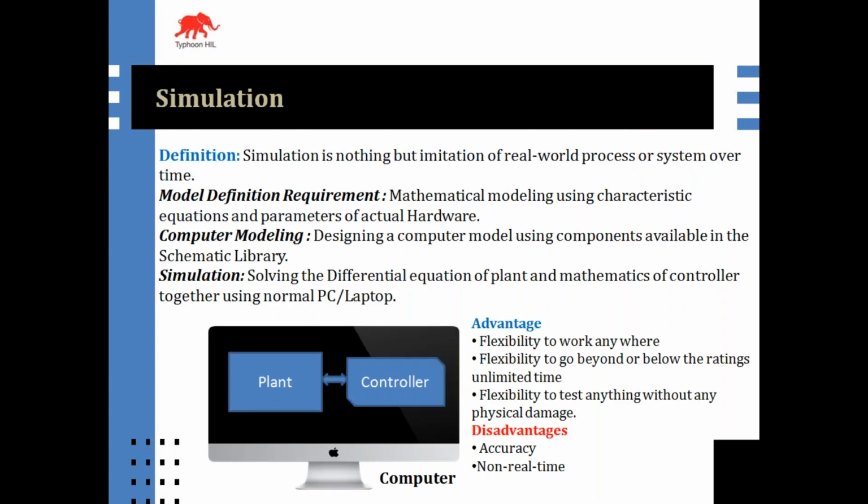I'll show you. This is the simulation part. Here, what we do first, we define the model definition, what we are going to do. We first define the mathematics for that, then we go for the computer modeling. Then we simulate for solving the differential equation of the plant and mathematics of the controller. So this is the plant and this is the controller.